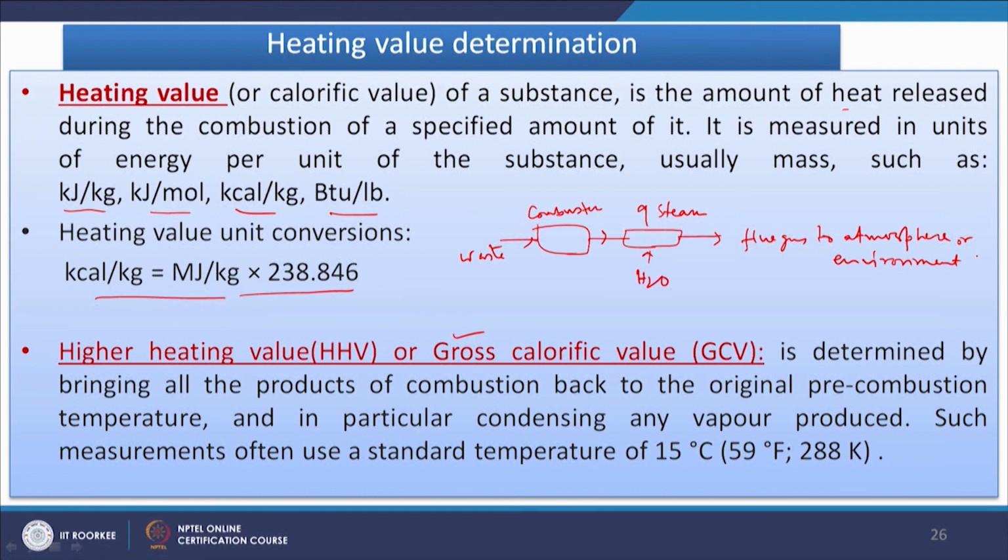Now, if we have a certain amount of material, then heat is generated here. After transferring the heat, if the flue gas temperature comes down to the ambient temperature, the same temperature which we had at the start of the reaction, then we can assume that all the heat available was completely recovered in this step.